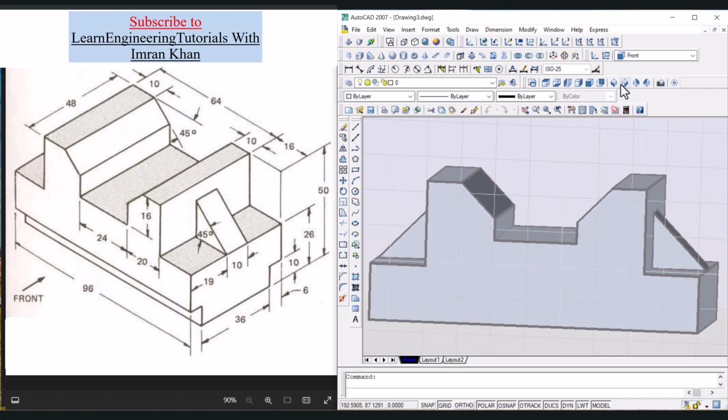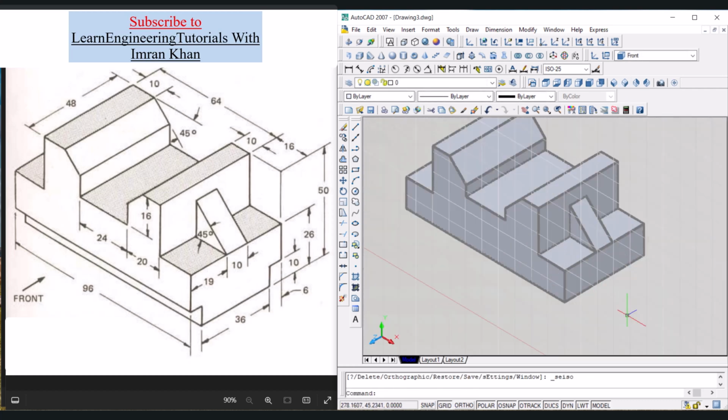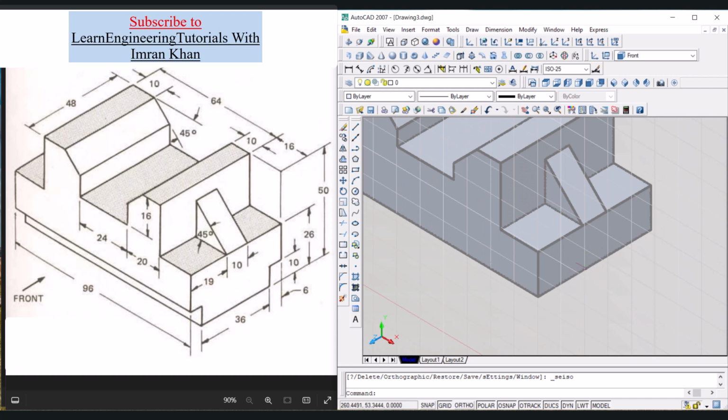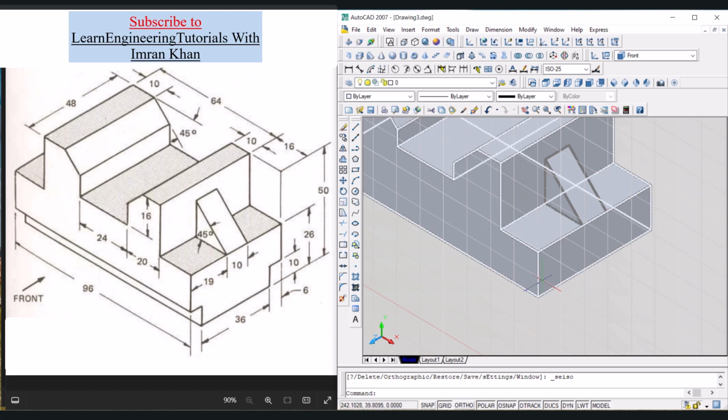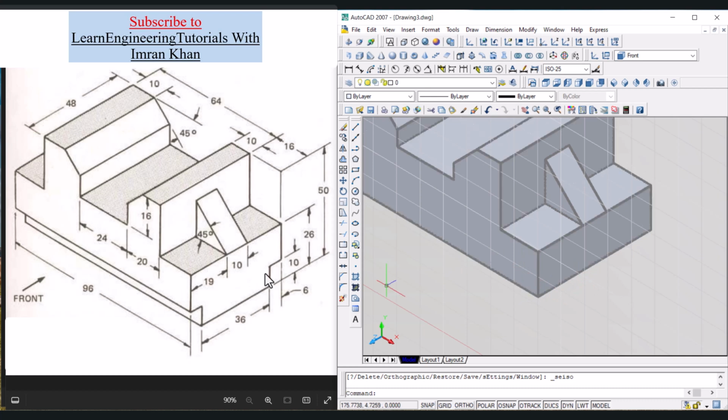Now click on this SE isometric view and now we have to draw a rectangle over here as well in the lower portion. What will be the dimensions for this rectangle? That rectangle will be on the center of this face and it will have a dimension of 1036. So click on polyline, click on this midpoint, move in this direction. Now why can't we move in this direction? Because the front view is selected in the UCS2 option. So press escape, select right side.